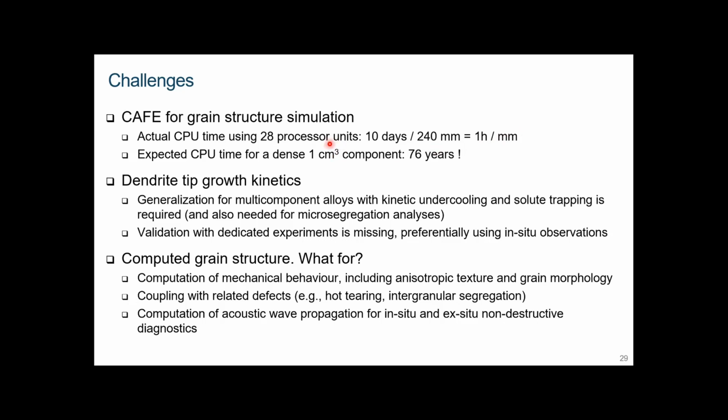In the big simulation I've shown you, it was 10 days. And this only represents a small volume of, let's say, less than 1 cubic millimeter. So if you would like to do a computation for a 1 cubic centimeter component by additive manufacturing, which is already quite small, but let's imagine this is of interest for you, you will need 76 years of computation. So my message is that it's probably not reasonable to think about having a full component, or maybe, of course, it must not be a dense component, and we have to find ways to change that.